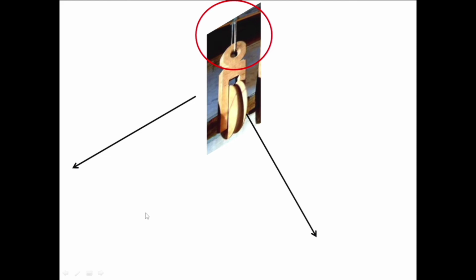When you are lifting any weight with the ship's gear, the center of gravity of the weight automatically goes to the block. And as we said, it is halfway through. When we talked about a homogeneous weight, it is half length. So this length and this length, halfway through would be the block. So the center of gravity would come to the head of the lifting gear. When the weight is suspended, the center of gravity comes right onto the point from where it is suspended.